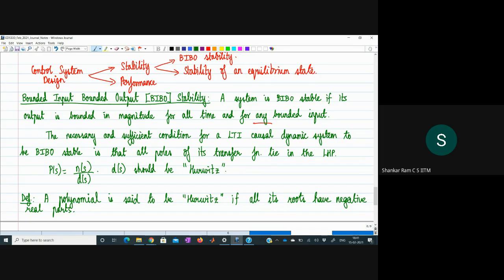But as I discussed, that is from the perspective of BIBO stability. When we look at another notion of stability, you will also gain a subtle distinction and understanding as we go along. As we discussed in our vehicle dynamics course, it doesn't matter even if the output is unbounded for one bounded input. Some may call the system unstable, so the choice is left to you. Typically it's called critical stability or marginal stability, with the understanding that it's not stable in the BIBO sense, but it's almost BIBO stable.